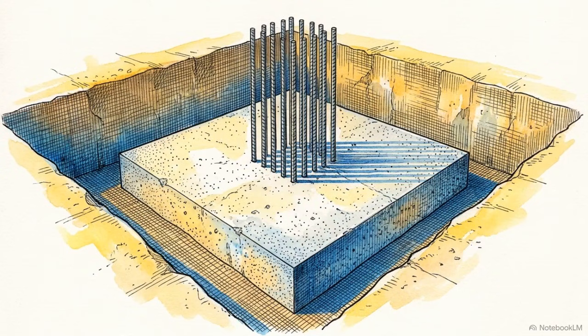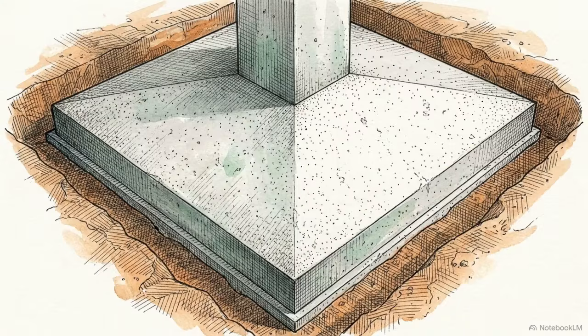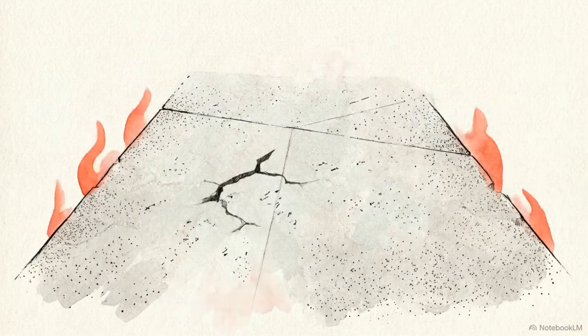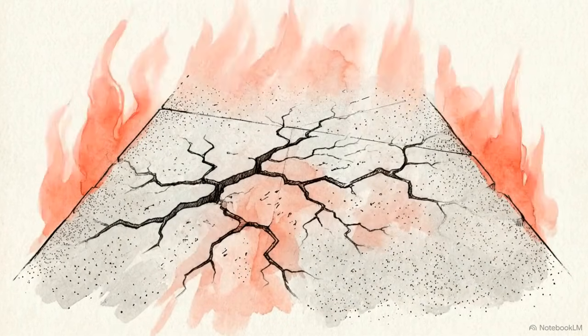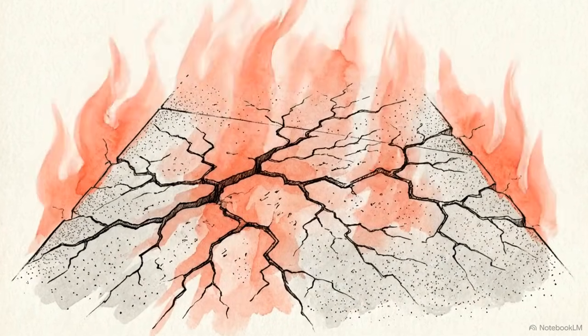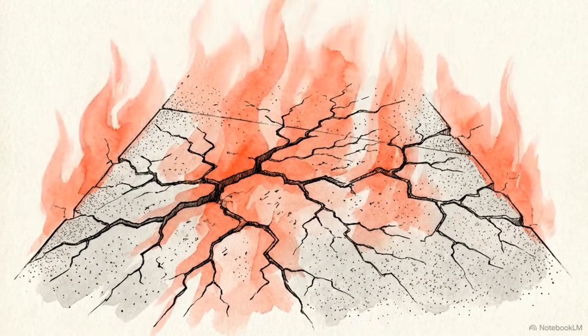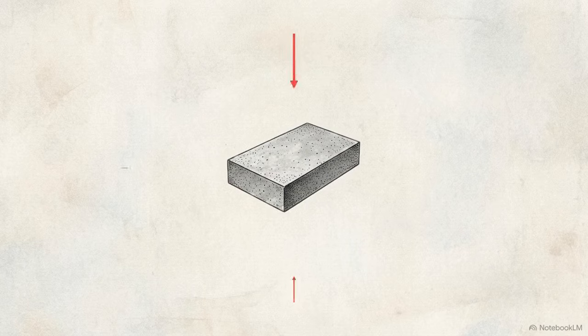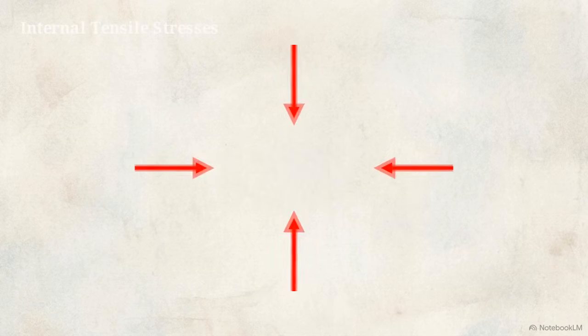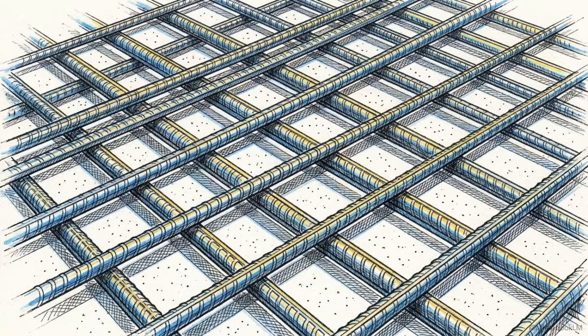Starting at the foundation, footings and flat slabs share a distinct geometric trait: a massive, expansive surface area relative to their shallow depth. This geometry makes these members vulnerable to volumetric reduction, driven by temperature variations and rapid moisture evaporation, well before they ever face a structural load. This phenomenon, drying shrinkage, induces severe internal tensile stresses that attempt to tear the slab apart from within.